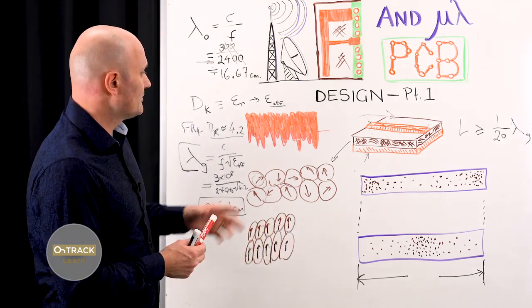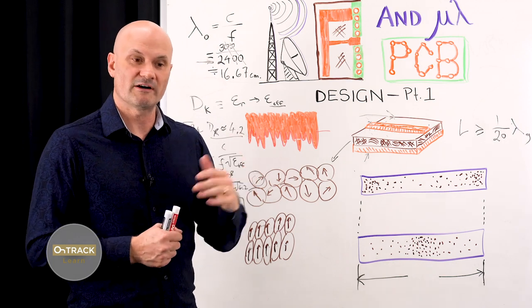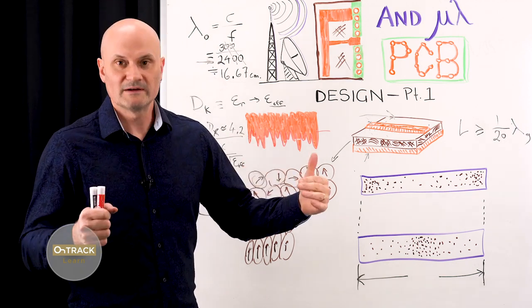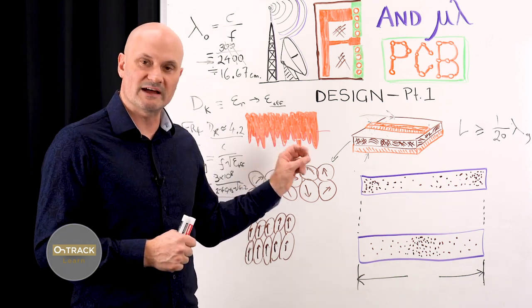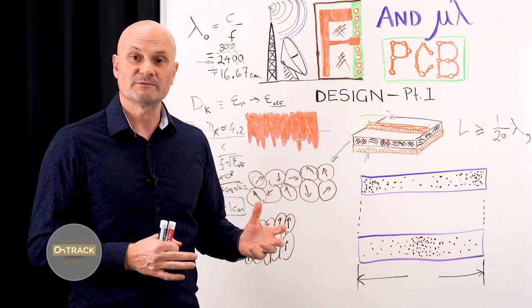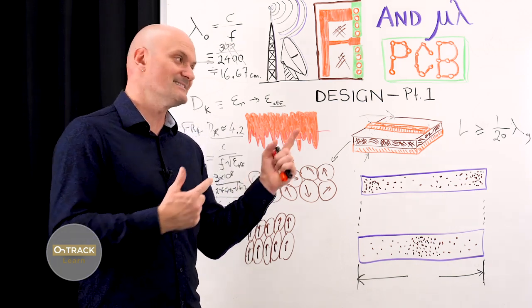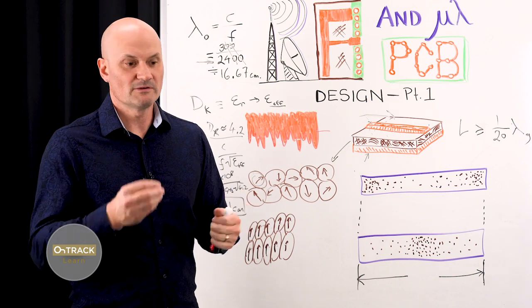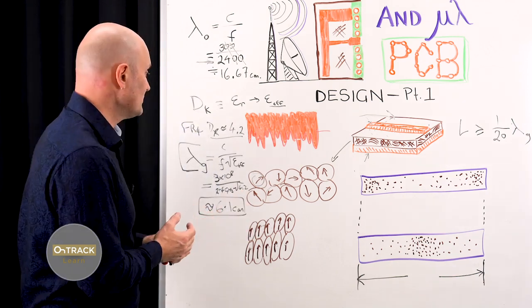And so we may decide, doing RF PCB design, if you're going very high frequencies, like above 10 gigahertz, you probably are getting into a realm where you start to need to use different types of copper, and you need to specify you want rolled annealed instead of electrodeposited, or you may even have a specific manufacturer part number for the copper you want to use.